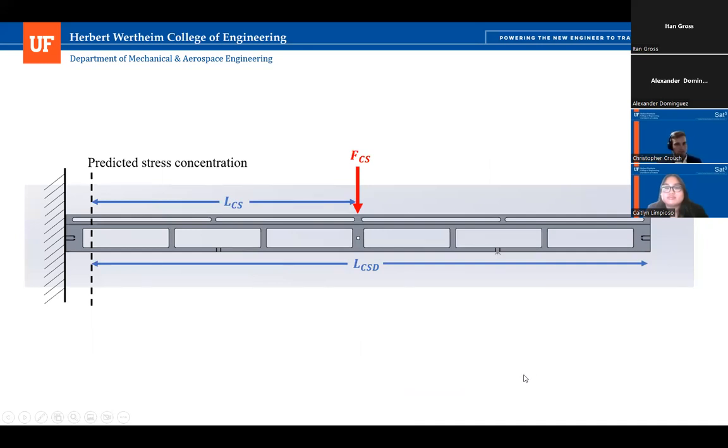One of the main aluminum parts that take the loads present during the launch, ascent, and orbit are the 8 rails that run the length of the CSD. During ascent, the maximum axial acceleration of the rocket expected is 4.1 Gs, and this is the largest acceleration expected at any point during the flight. Due to the mounting orientation of the CSD on the Z face, this axial load on the rocket translates to a longitudinal load on the CSD relative to its own axes, and this can be modeled as a simple beam.